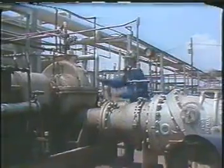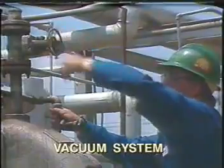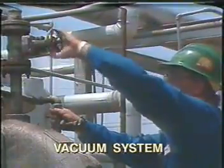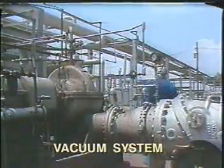Many facilities have a central vacuum system which is used for priming pumps. There is a vacuum line connected to the pump discharge line, and to prime the pump, you open the valve on the vacuum system.